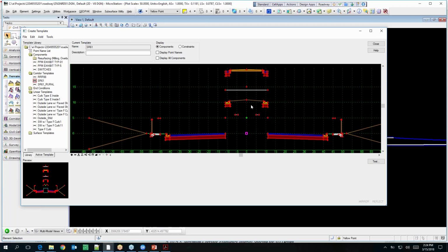So why would the contractor, if he's using a different option, use our bottom surface? Why wouldn't he just take our proposed and say, I'm using option 10, that's always 11.6 inches below my top? He probably wouldn't use it for his automated machine guidance. He might use it for quantities, because if he knows which option we use to calculate, he can then calculate whatever option he wants to choose.